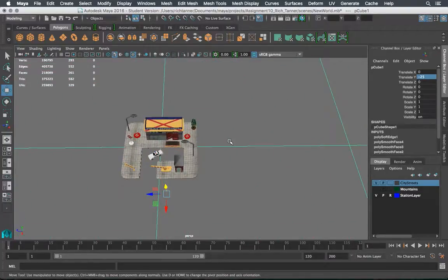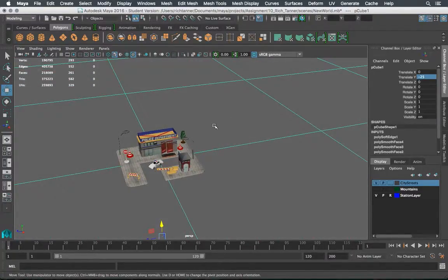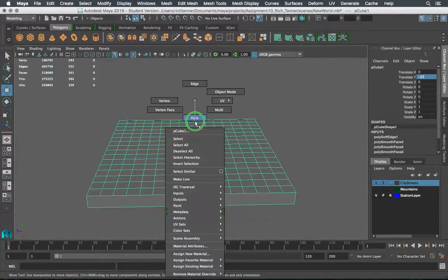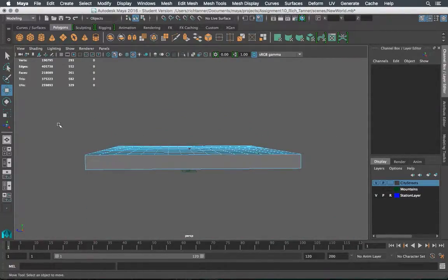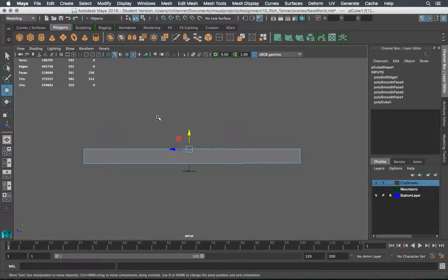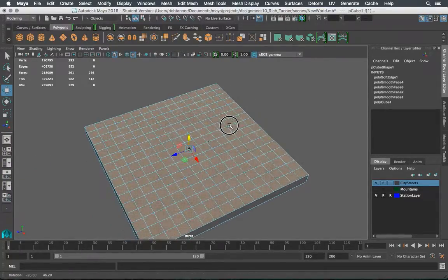And so what we've got is, if you can see these cubes, these squares that are subdivided. It's a rather large city block, but this is a small police department, so that may work. We can add in buildings around it or a big parking lot, nice lockup, something. So we're going to go with what we've got. I'm going to go back to face mode. I'm going to select everything, and then use control and drag to deselect those. So I should just have the tops.